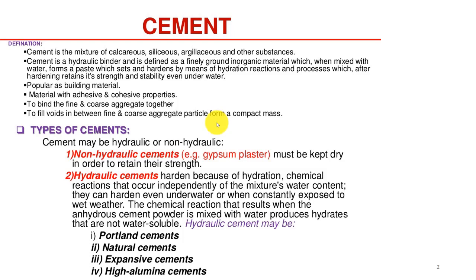Then you have argillaceous rocks. Argillaceous rocks are basically the combination of siliceous and aluminous material. So argillaceous might be of any clays. There is a vast majority of clays that you can use in cement. Clays have a lot of silica content and alumina content and some alkali earth materials in them.